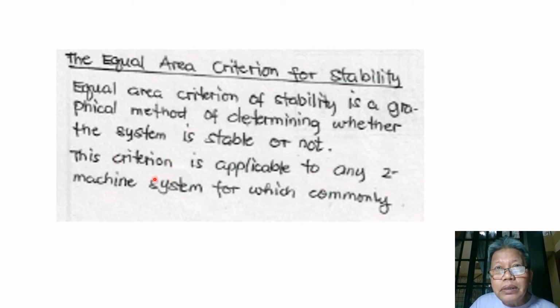But when the roots of our characteristic equation are real and distinct, meaning we obtain two roots for our characteristic equation, this means that when the synchronizing power is negative, meaning at the right side of the sine curve, then we have seen that our generator will be at an unstable condition.